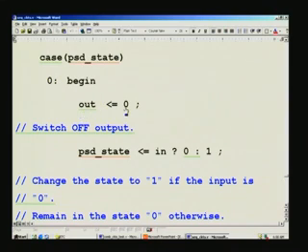That is what we have seen, and once again we use a mux for this state for determining the next state. It all depends upon the in. If it is 1, we need to remain in the same state, that is what we have seen in the figure, and otherwise we wish to go to the S1 state.